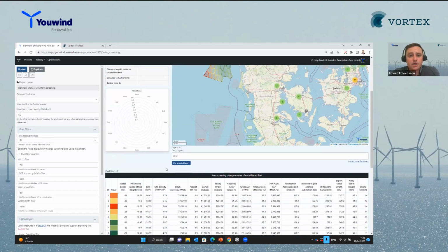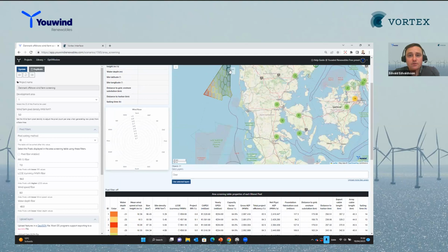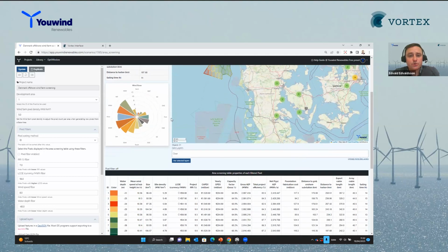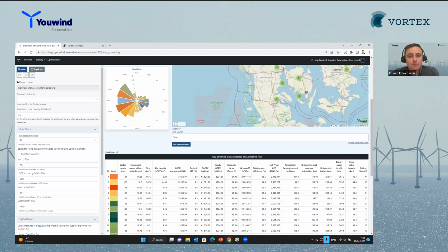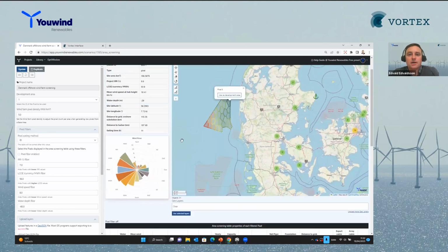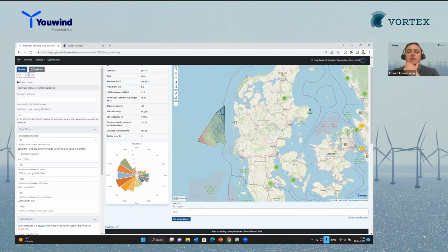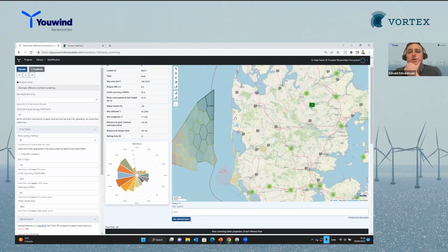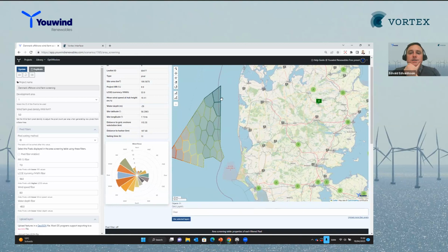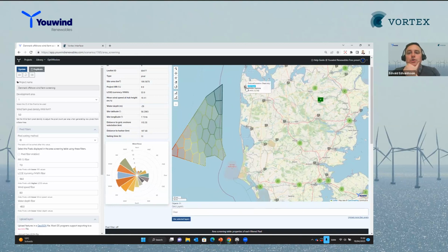So as you're mentioning here, for each and every area, we calculate the wind speed distribution and the mean wind speed at hub height with the different areas, and all the different costs and technical components, including the total project efficiency. And this is extremely important as well when we're looking into the second part here, which is basically where are we going to connect this very big polygon or the different aspects here to an onshore grid.